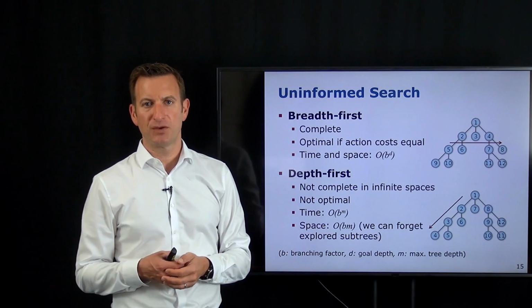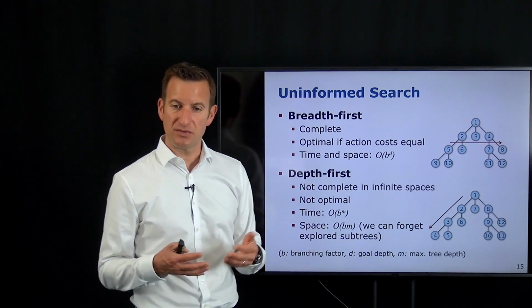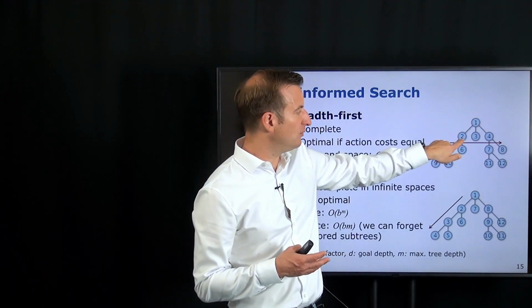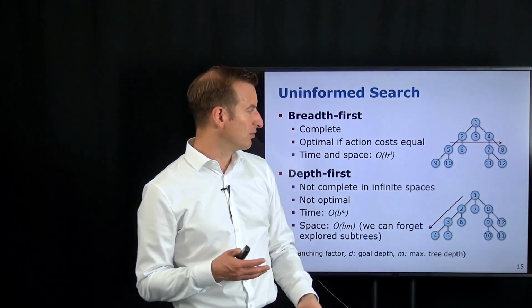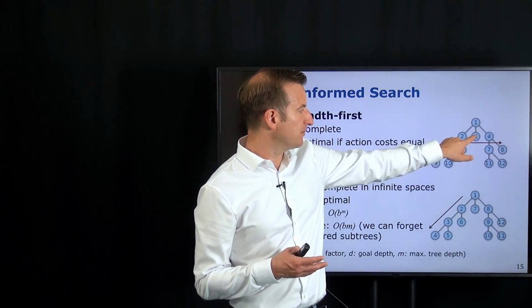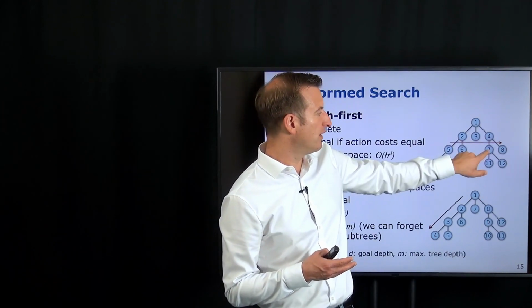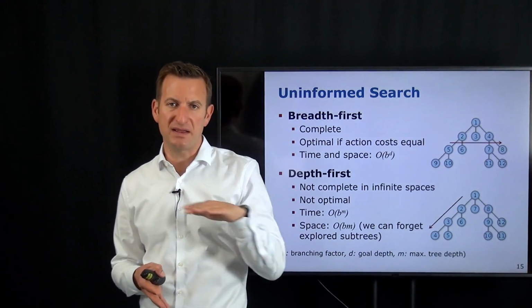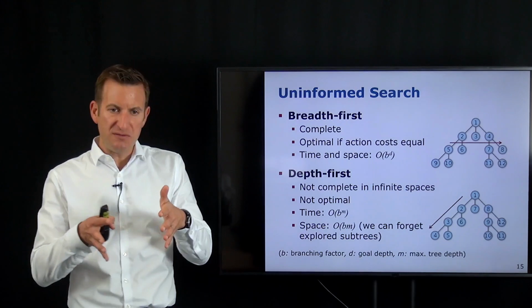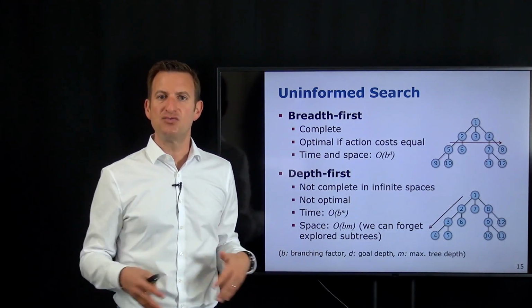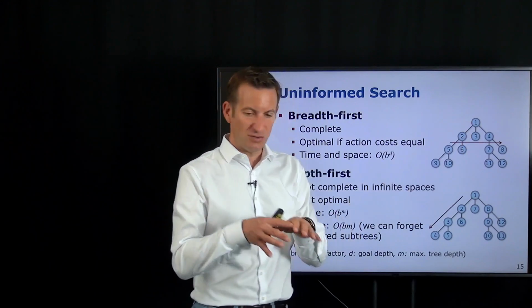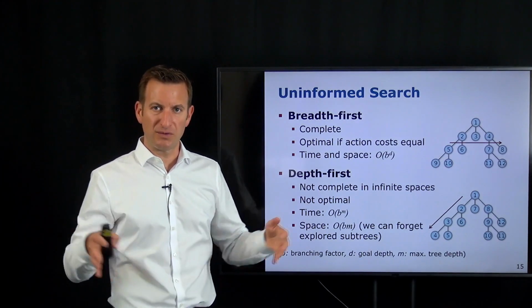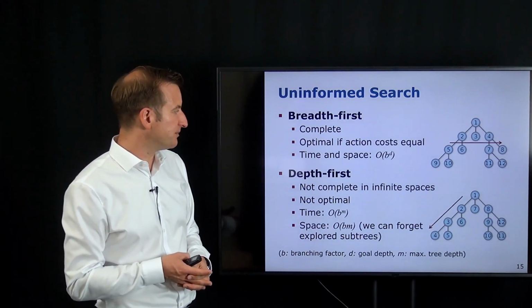So in which order do you actually search through those states? You basically go level by level. So you will start at 1, you expand 2, then 3, then 4, and then you look at the neighbors of 2, which are 5 and 6, then 3, which has no neighbors, then 4, with 7 and 8, and then 9, 10, 11, 12. So level by level, you are expanding that tree. And thus you basically uniformly extend your radius. If this is your start location, you're basically building, at least in the 2D world, concentric circles around the current configuration until you reach your goal location.